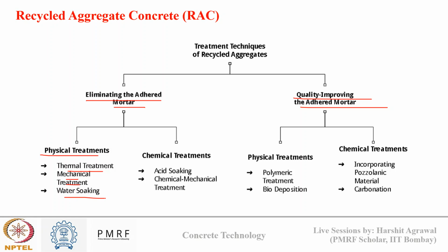Or using water soaking. Water soaking can again make the adhered mortar weak so that it can be removed. Then there is chemical treatment like acid soaking, or chemical mechanical treatment. So these techniques are also used to eliminate adhered mortar.